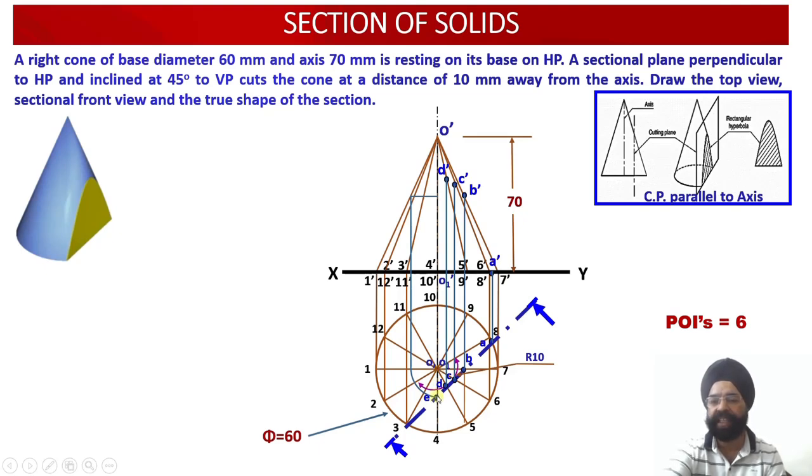Here we have the radius available, we have transferred the radius to the 90 degree angle, that is onto projector O1. After transferring it onto the projector O1, now I am going to take this upward and it will be met on the projector O dash 1 dash. So from this point, if I draw the horizontal projector, I get the height point corresponding to this point E. So the front view of the point E has been located over here this way.